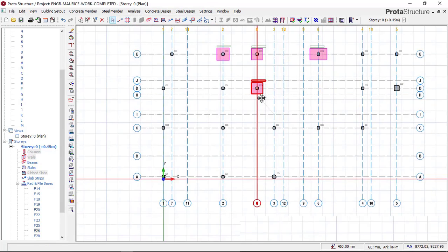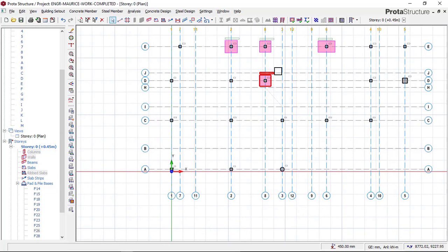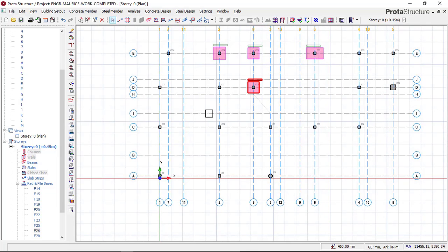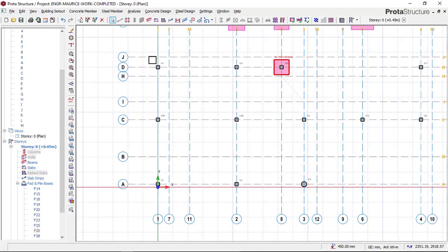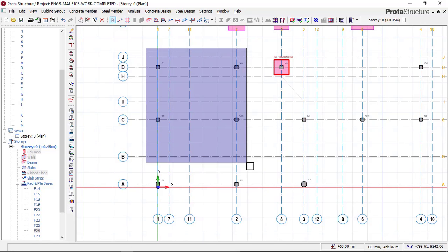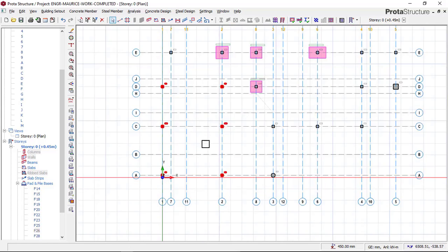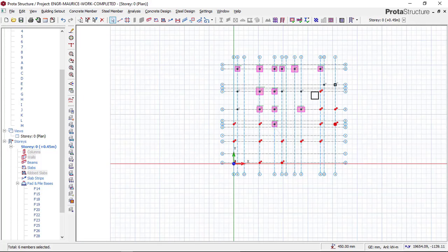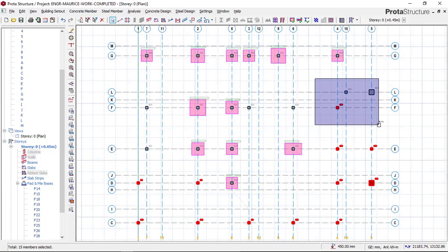So knowing that right now, you must design for the foundation individually and not as a group. But for the base of this tutorial, just to make it faster, I'll highlight all my columns and design them at once. But for a live project, if you're doing it for a client, never do this.